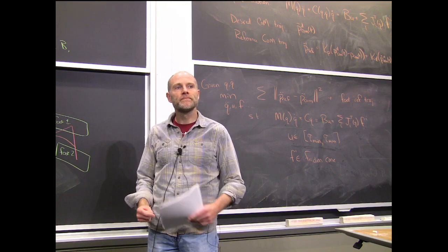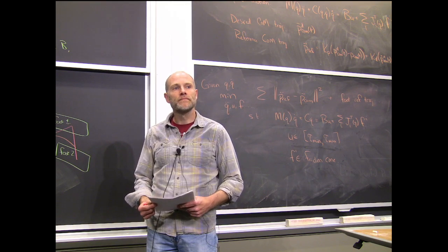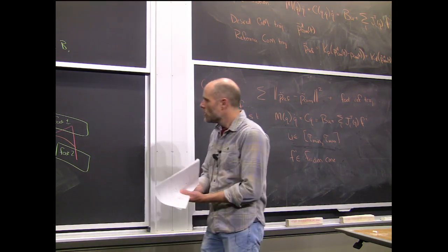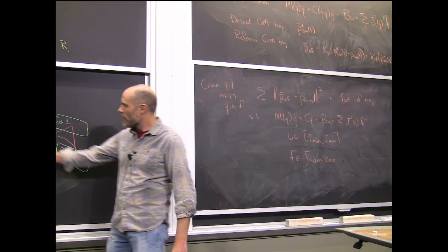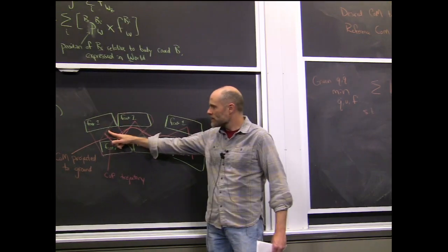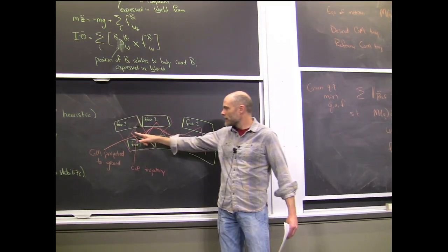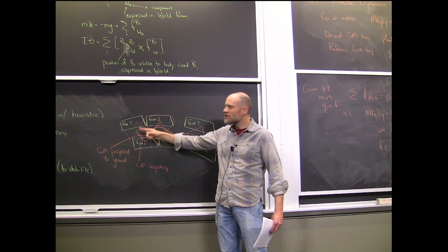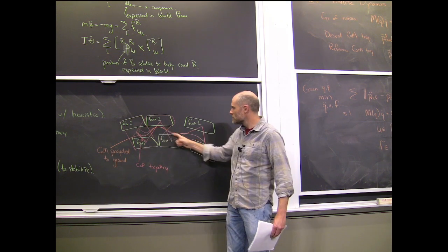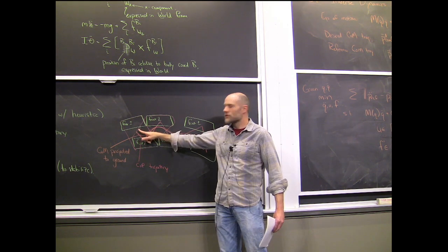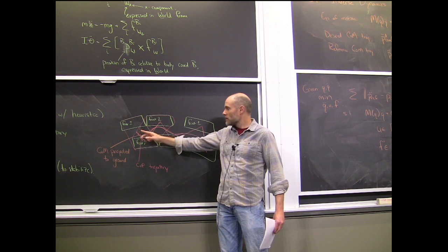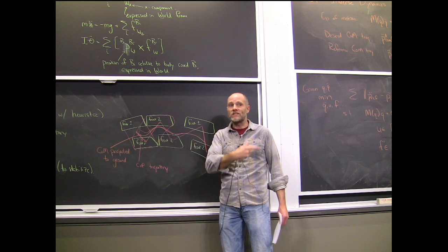Could you elaborate why you need additional PD controllers? It's roughly this: if your initial center of mass trajectory was this orange one, and you find yourself in a different center of mass location, it's just a way to interpolate the original center of mass trajectory into something that's relevant for your current time. The reason you need to do that is because we're commanding accelerations, right?